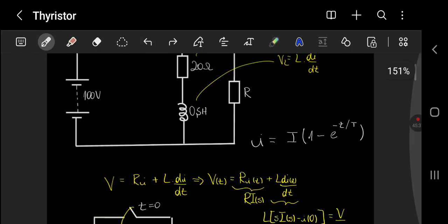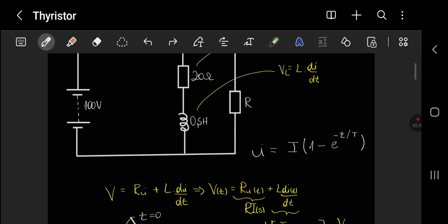If you substitute the values right here, you're gonna find 10 milliamps. After 50 microseconds, the thyristor could not reach the level of latching, being 50 minus 10 milliamps, which is 40 milliamps, which is less than the level of 50 milliamps necessary to trigger the circuit.